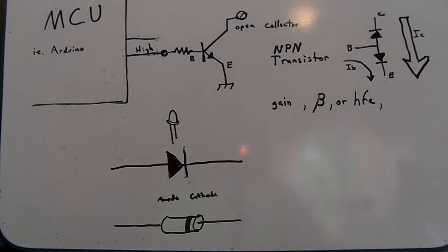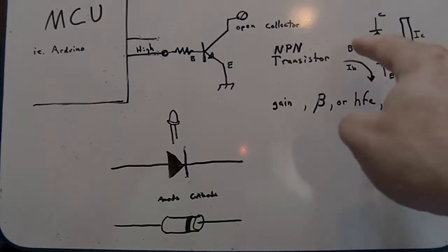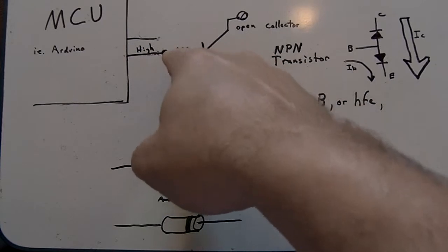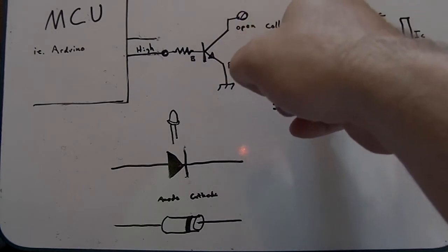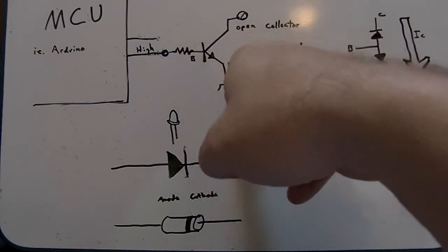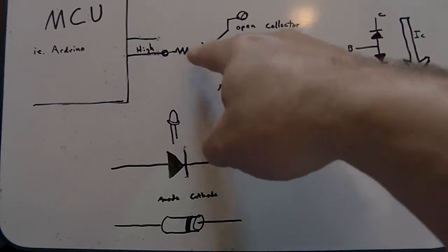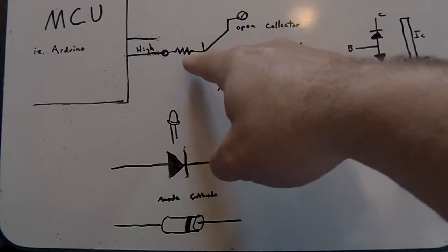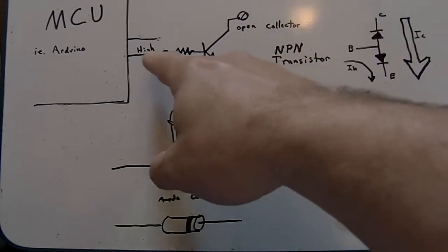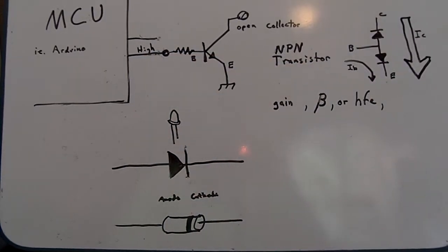Now a big old dumpy power transistor may have a beta as low as 20. But typically you'll see something more like, say, 100. So 10 milliamps going through here, then I could flow 100 milliamps. I could flow a full amp going this way if the transistor was rated heavy enough. So a transistor with a heavy enough rating, I could switch an amp with only the 10 milliamps off the pin. And I can probably pull, these pins are made to pull, maybe in the 20 milliamp category for LED, not a whole lot more.